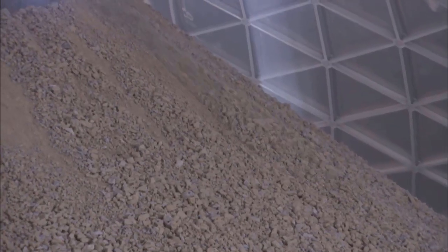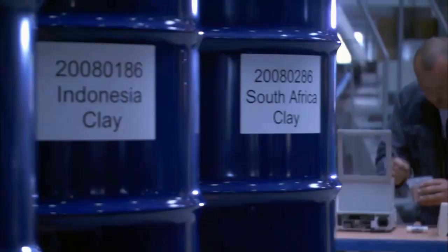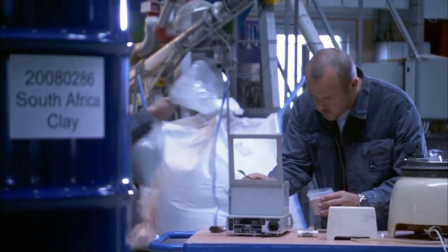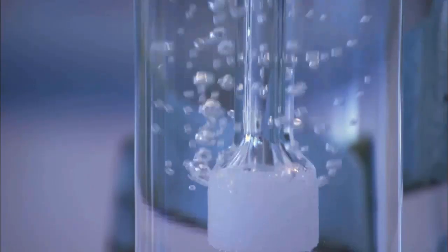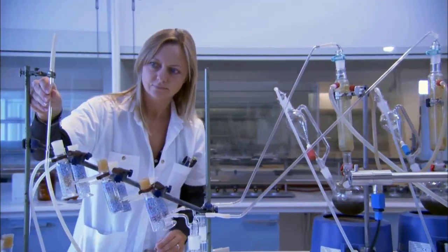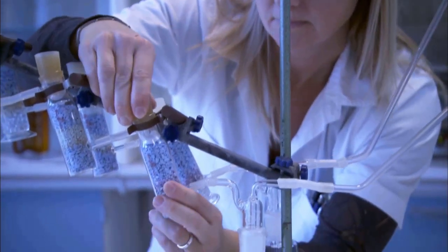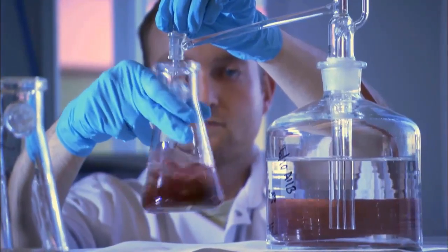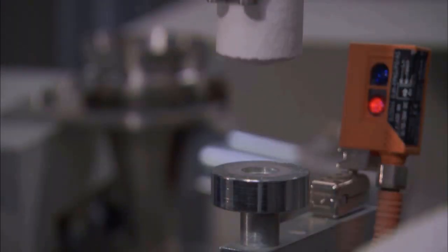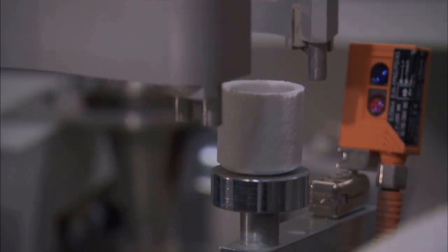The composition of limestone, which is generally the most important source of calcium, will determine all the additional raw material requirements to be selected. The main objective of the design and preparation of raw materials is the kiln feed, which enables the effective and energy-efficient production of Portland cement clinker.